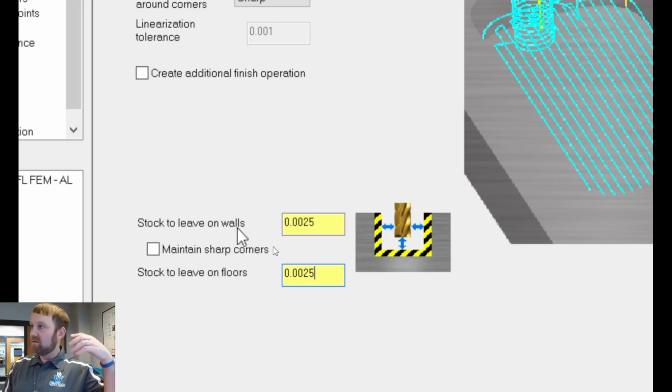Once it goes in, you're good. Your depth has to be 1/4 inch deep because we're going to be holding on to 1/4 inch of the part. We've got to get the overall part to 1/2 inch thick, which means there better be a 1/4 inch sticking out of the top of the vise jaw.